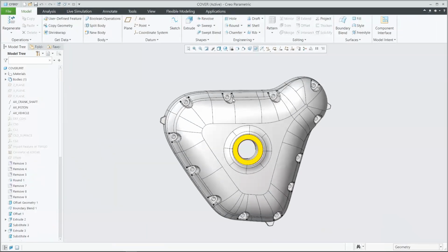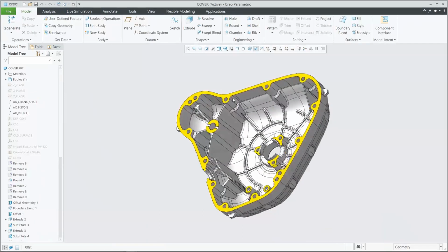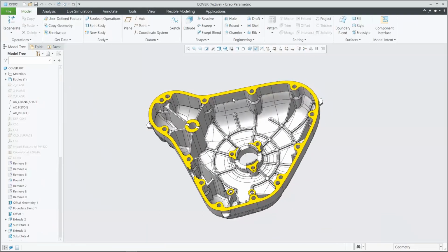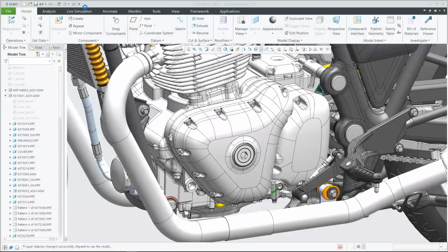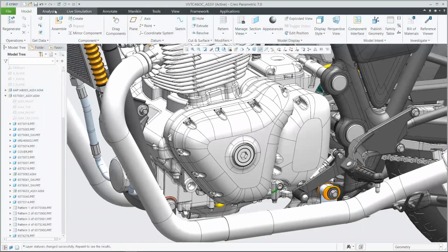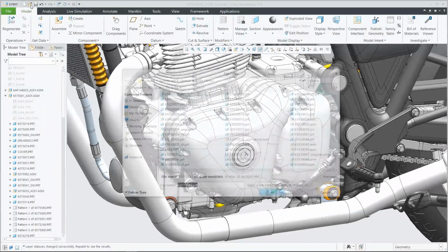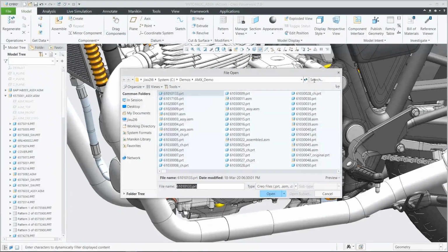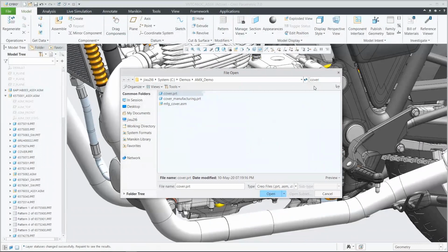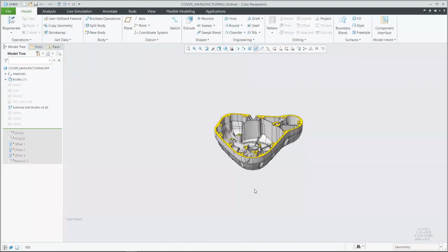Now, this is actually a fairly complex piece. It would normally require a lot of work to cast and machine all the different holes that you see here and all the features, or even machine everything from a stock piece. So what we'd like to do instead is use additive manufacturing to create the piece. What this does first and foremost is allow us to work with materials that might not normally do very well with something like a casting, but we have no problem whatsoever using on our metal 3D printer.